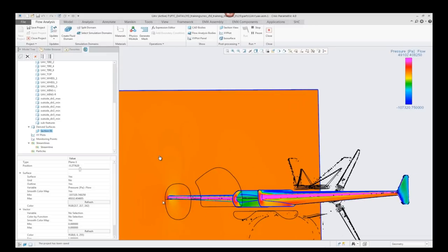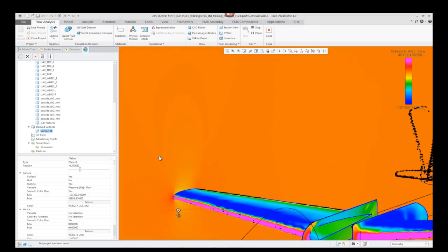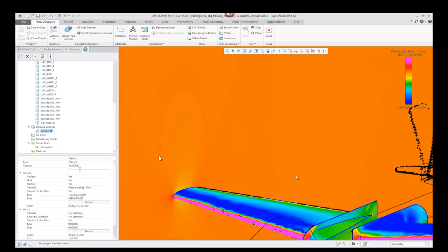So if you're looking at something like, not just a wing in this circumstance, maybe you're looking at something like a motorcycle, an off-road cycle that has a large mud guard on the front. Is that going to be giving you a lift problem as it's traveling forward at perhaps a motorway speed, where it's going to make the front wheel too light? And that's the sort of information you can derive from an experiment such as this.